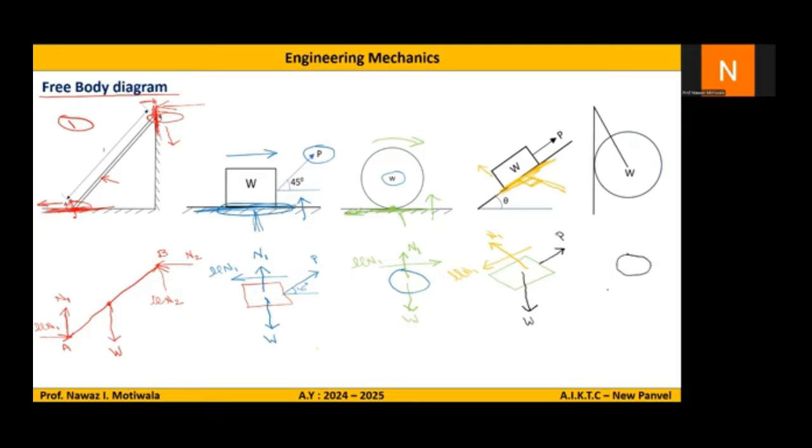The first thing which we have to show is the applied force. Now, if you observe this figure correctly, there is no applied force given as such. But this entire body which is given in the diagram is being supported by this particular cable. The cable will always give the tension force and it should always be shown away from the body. So that can be considered as the applied force. I will make a force like this along the thread length. I will name it as tension in the string.